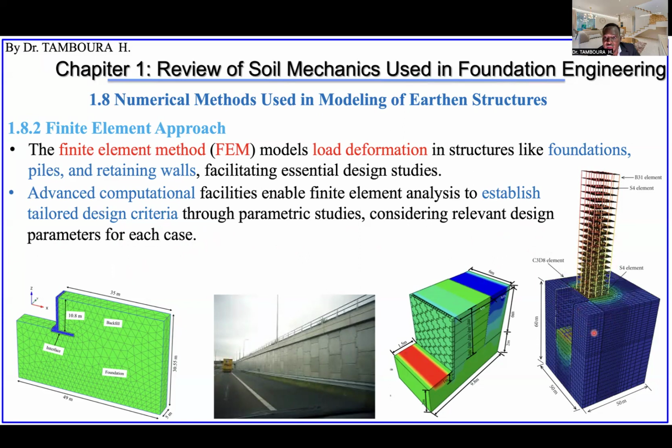You have to consider the soil parameters: Young modulus, unit weight, cohesion, internal frictional angle. Of course, the weight of the building and the different loads, static and dynamic loads, everything. And dimensions. If there is any neighboring building or structures, the rigidity of this wall.